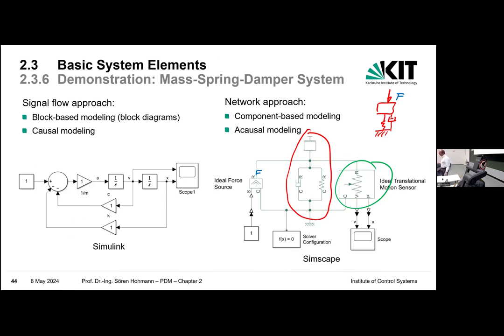And if the driver presses the pedal, the machine should brake, but you don't need additional hydraulic braking, so you have to reduce the hydraulic braking in correspondence to the electrical braking, which makes some sort of interference with that. You need a completely new braking system, which could be fail safe, etc. And then the question is, how do we do that? At that point, it was quite difficult because people at that time said, well, it's important for safety reasons to always have a hydraulic connection, or two, better to say, two different and separated hydraulic connections.